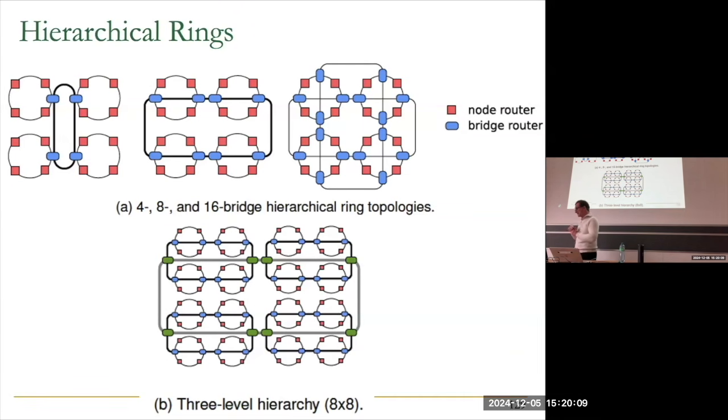But I should also say that, if you think about it, snooping is a higher level choice. You can think of this as the physical implementation, right? This is how the network looks like. But snooping, the assumption of snooping is a virtual assumption, meaning it doesn't really require a physical bus, as long as you can guarantee with some other techniques that you can do snooping.